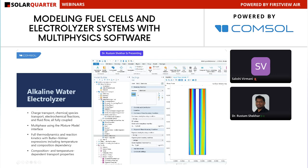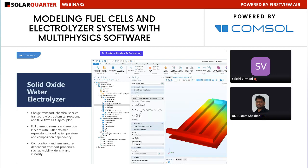So when we solve all these physics, you will get the details and output related to those particular physics. If you talk about charge transport, then you can see the current generation at local areas. You can see the mass distribution or the species distribution, and by solving chemical species transport, you can see the electrochemical reactions happening, which can be competing reactions at a particular surface. So you will get the degradation. Degradation also can be modeled, which can take up some of the potentials. So you can see the enhanced overpotentials, and vice versa.